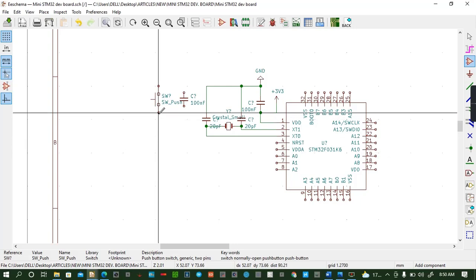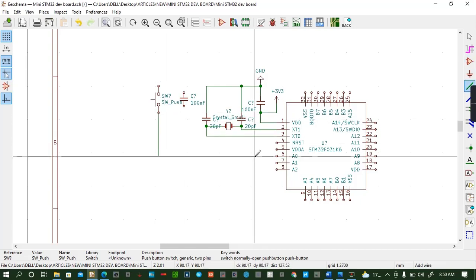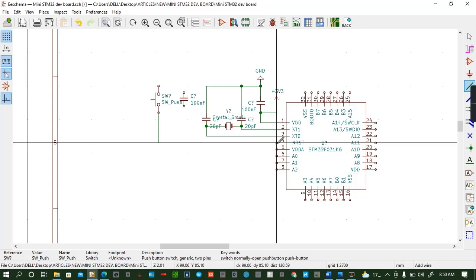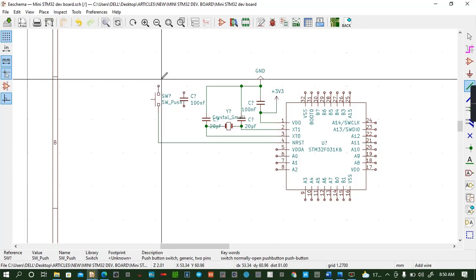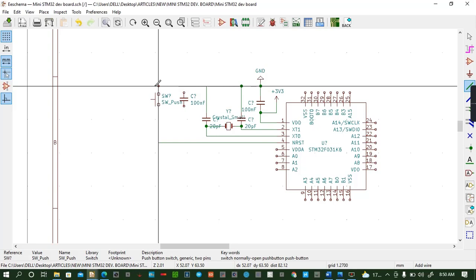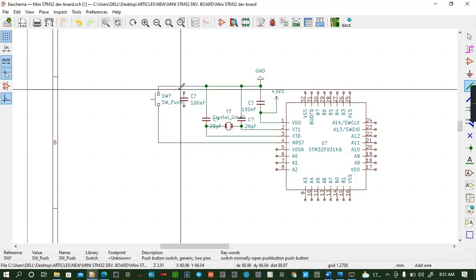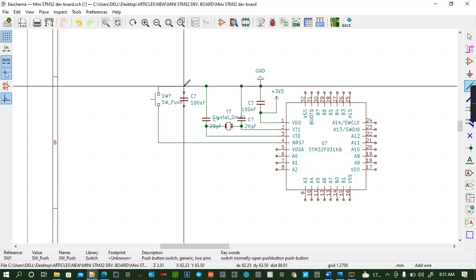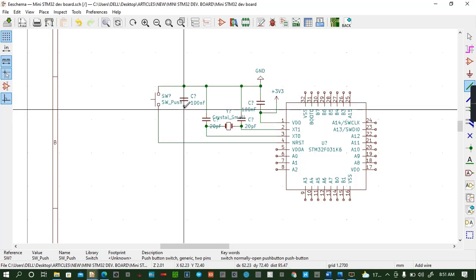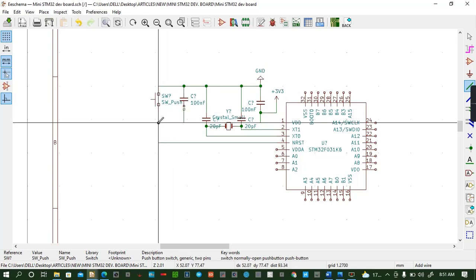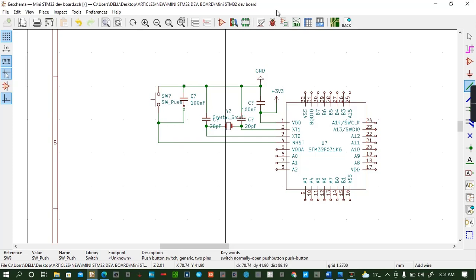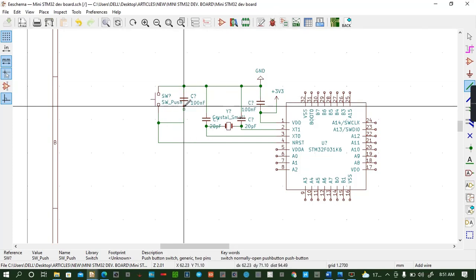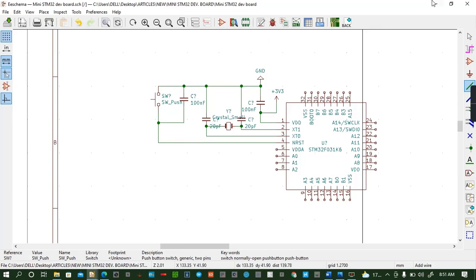So we have this switch connected to number 4 wire. It goes all the way to pin number 4. Then we have this one connected to ground. Like that. This capacitor is grounded too. Like that. Then it comes from here to this. All these ones are filter capacitors or coupling capacitors. Okay, sorry, not connected, so we can finish the connection like that.